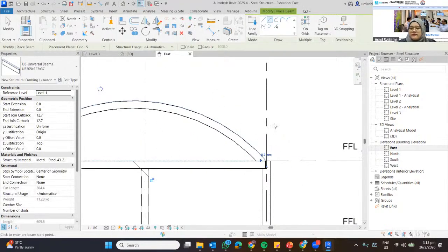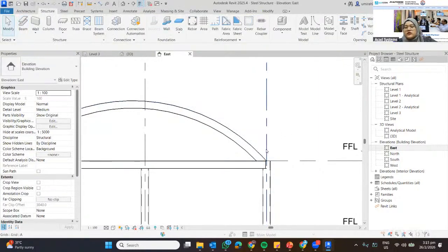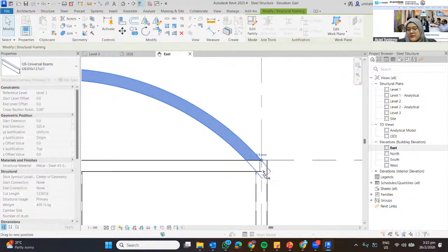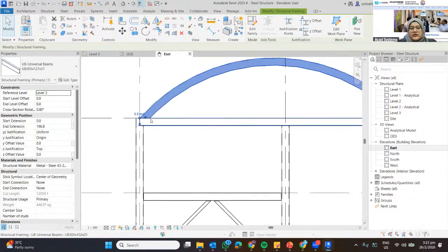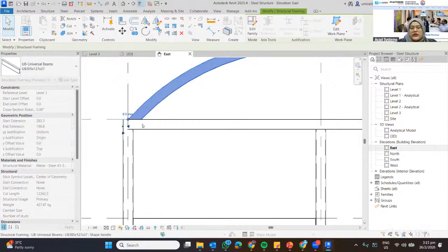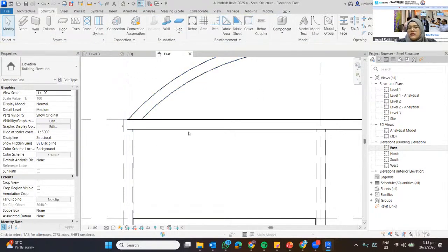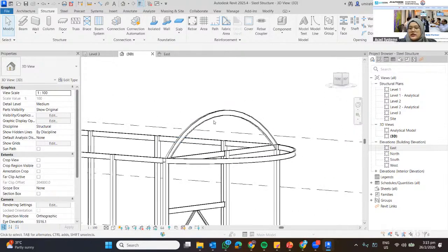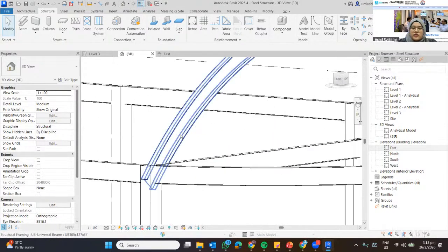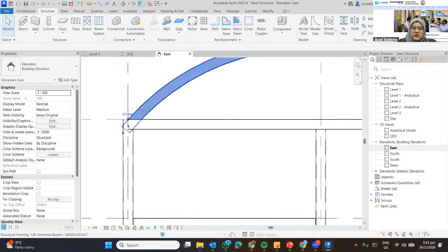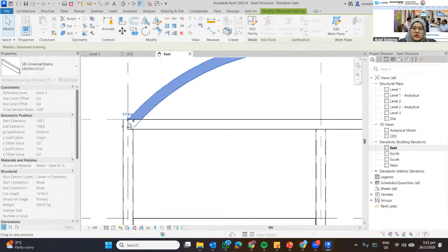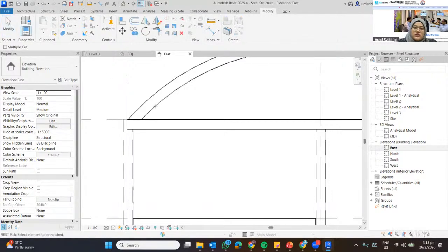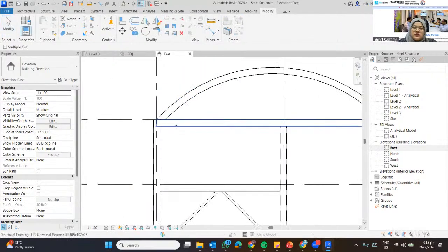All right. And then it's the same as you draw in horizontal. You want to drag the beam longer. All right. You can also do that. And then you can also do the notch just now. All right. So it's here. You can see this is the curved beam. Then I can do notch just now. Let me do the notch. Okay. So click on modify, notch, click the tools. You can see it will cut.